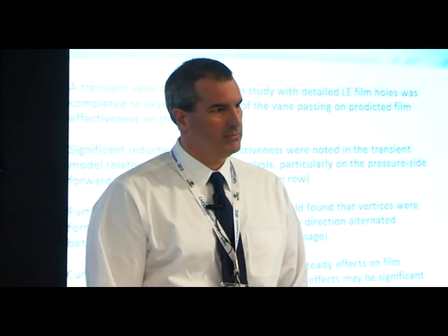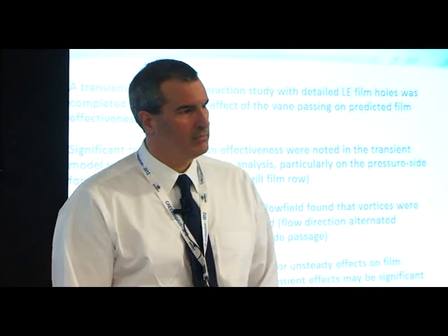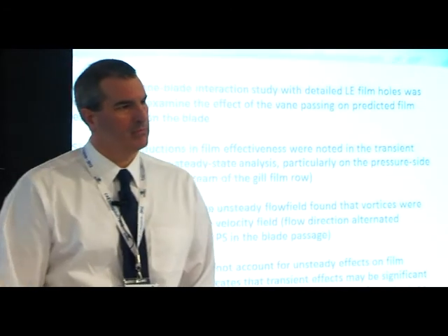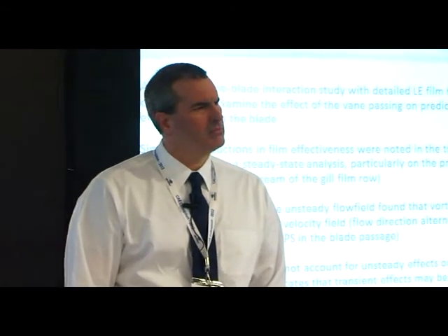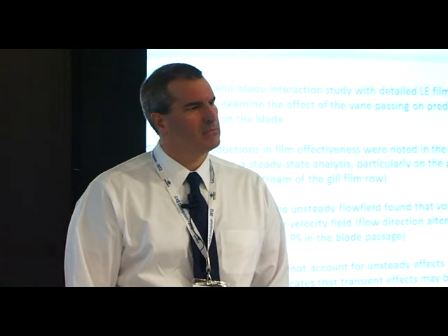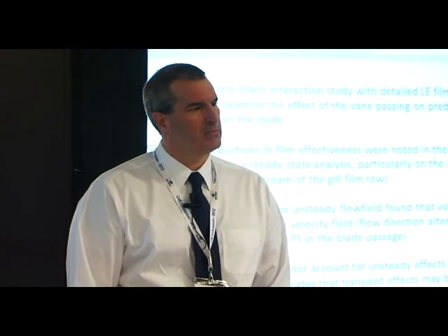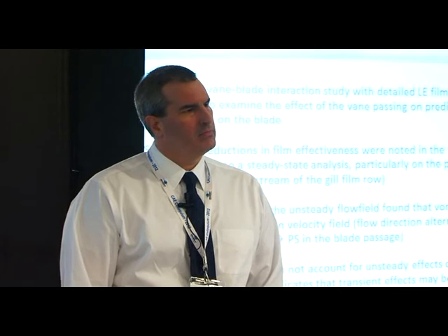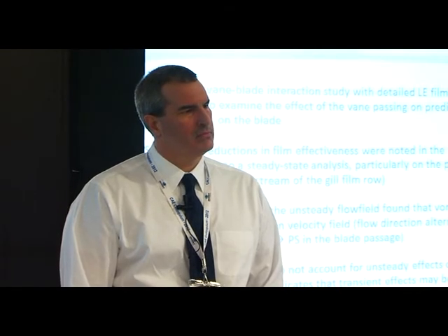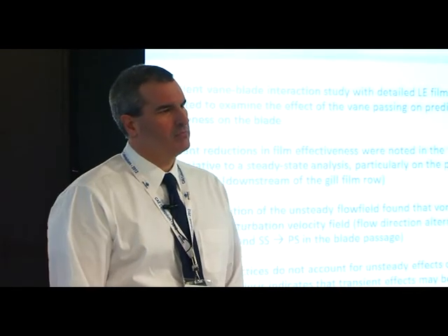Thanks. When you said you have done the transient analysis in CFX, you have taken only first order in time step. First order in time step would actually nullify the transient time, so you can't capture the time with an accurate sense. It's only first order. In time, you are looking at a truncation error which is very high.